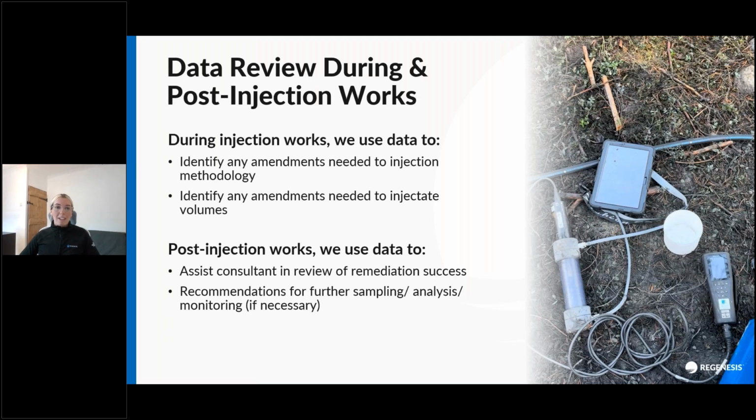So what about data during and post the injection works? One of the key factors for our clients upon completion of injection works is access to that injection data. And as such, it's critical that we have a robust data management procedure. During the injection works, we collect a range of data, including the injection pressures, flow rates, injection volumes, a commentary on the works, our placement validation data, and groundwater monitoring.